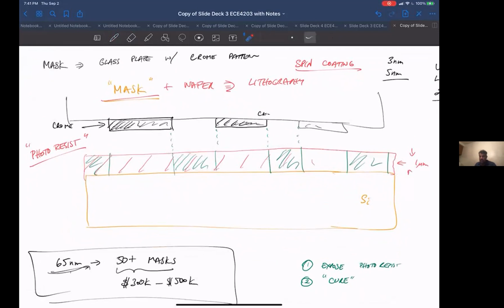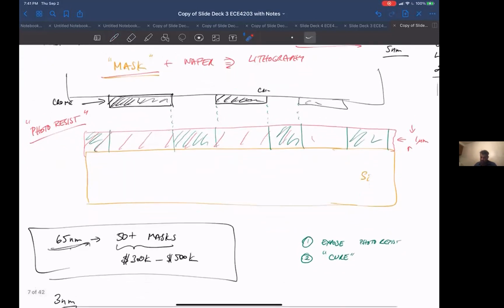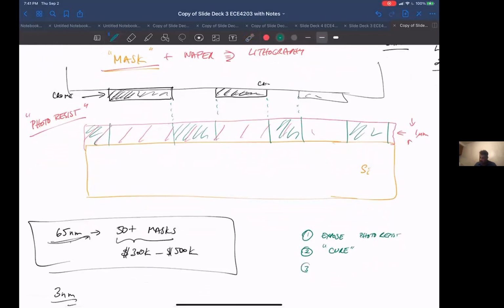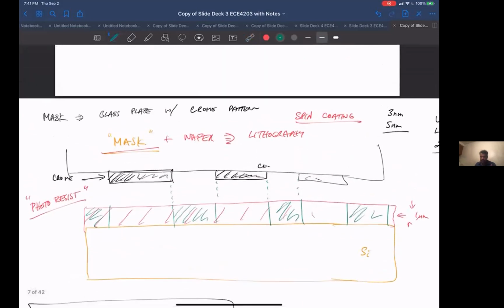And then you go through a process called lift off. There are different processes, but it's a chemical wet process. So now you dip this wafer, or really spin on some other material that removes the resist that's not hardened, but leaves the resist that is hardened. So the resist that's hardened through the cure and exposure stays on.